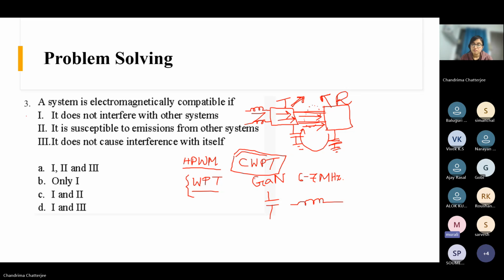One sniffer has a bandwidth of between 1 GHz or something, and it will sniff the signal only within that range, not more than that. So we create multiple levels of sniffers and identify where exactly the emission starts. The spectrum analyzer will give you some quasi peaks, and we interface it with the matched attenuators.